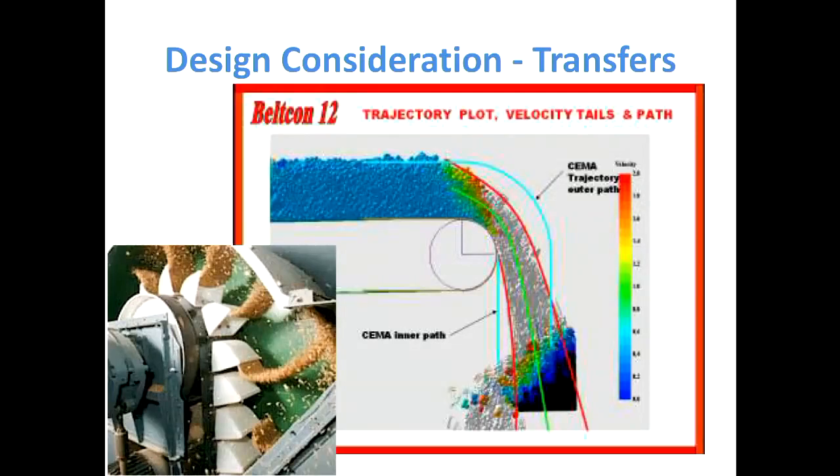But with bucket elevators, most people do not realise how centrifugal bucket elevators work. They think that the material comes out of this bucket, falls onto this one and is slowly discharged later. Yet, with you being mechanical engineers, as soon as you come up here and get into that curve, you're starting to get the acceleration of V squared over R. So here at 9 o'clock coming up, that's when the material starts moving in the bucket, and probably at about 10 o'clock is when stuff is actually starting to come out. A lot of engineers have absolutely no idea that that's what's going on. So this is a good picture, and I surprised a lot of people with that.